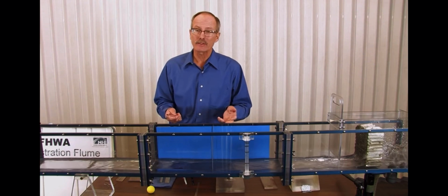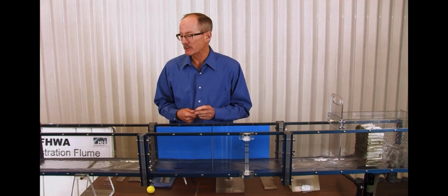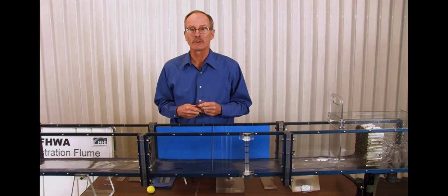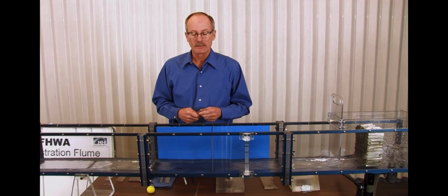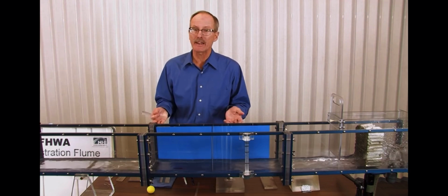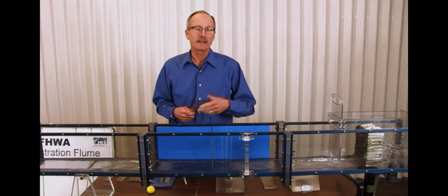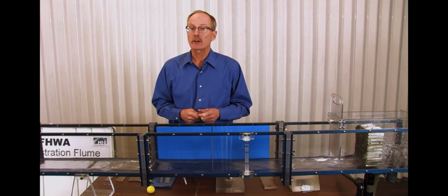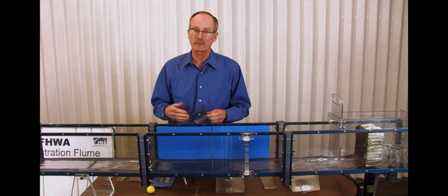Because if we're not, the calculations we do will not reflect what's really happening on our project, particularly if there's something that's keeping the channel from doing what it would normally want to do. So, an important underlying assumption of Manning's that is often forgotten: we must have steady uniform flow. If we don't, a more complicated analysis, typically called the standard step method for gradually varied flow, and implemented by a computer program, for example, the Corps of Engineers HEC-RAS computer program, does backwater surface profile calculations for gradually varied flow.